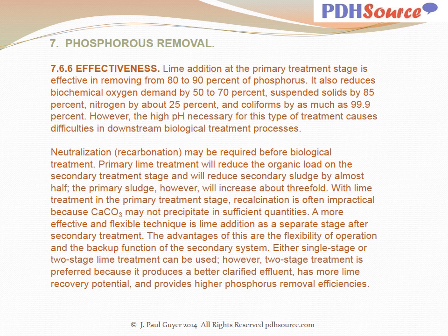Either single-stage or two-stage lime treatment can be used. However, two-stage treatment is preferred because it produces a better clarified effluent, has more lime recovery potential, and provides higher phosphorus removal efficiencies.